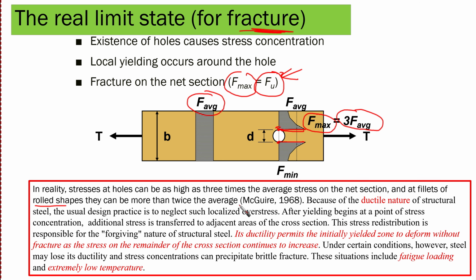Okay, so because of the ductile nature of structural steel, the usual design practice is to neglect. Take care of this word. It is very crucial here. Is to neglect such localized overstress. So the overstress here is going to be neglected, intentionally.